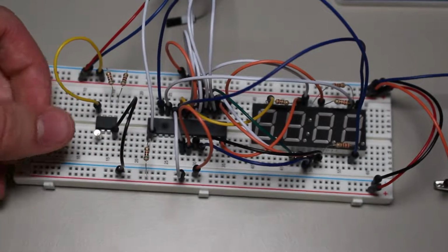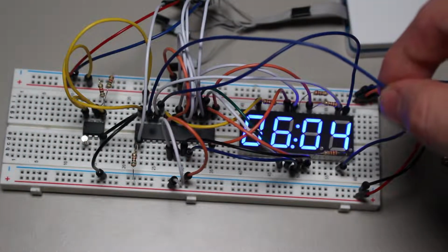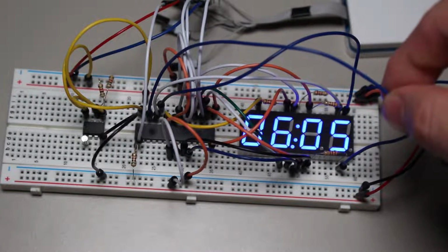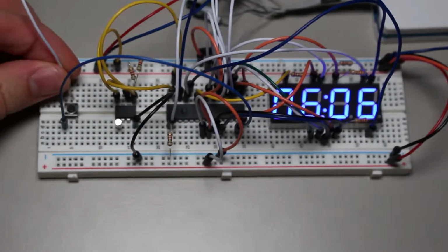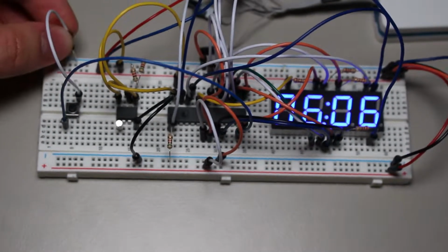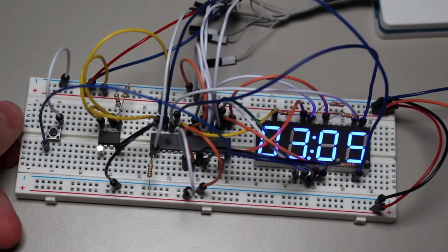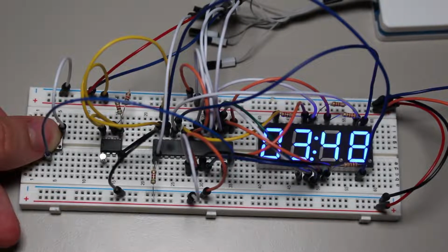After writing the code on the microcontroller to read from the RTC, we can see that it is working. For this project, I will be using 24-hour time to remove the need for an AM and PM indicator. However, we still need a way to adjust what time it is just in case the clock is wrong. And for that, I added a button that will quickly add time to the timer. The result from that button press is then written to the RTC's memory.